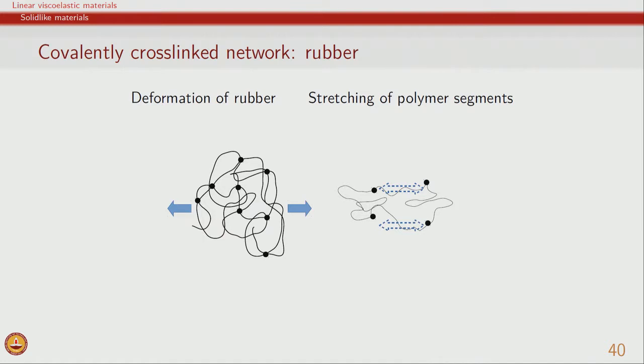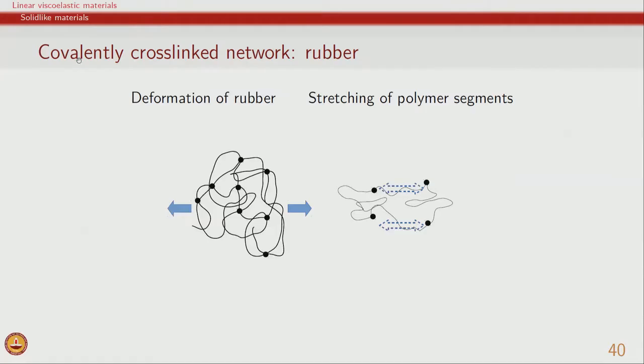The networks of polymers we have encountered several times in the course so far. We could have a polymer solution which is concentrated and has very significant polymer interactions. We of course discussed entanglements in the context of polymer melts. In these cases the interactions between polymers are physical. They would be mediated interactions based on hydrogen bonding or electrostatic interactions or van der Waals interactions and so on. And so the network that is formed in either a polymer melt or solution is a temporary network, or a network with temporary junctions. However, a cross-linked rubber on the other hand has covalently bonded cross links.